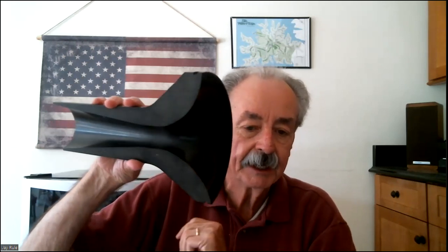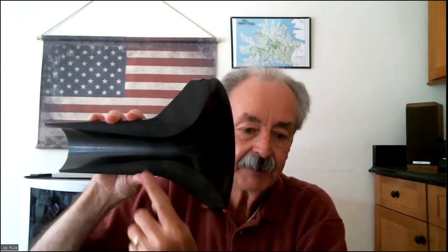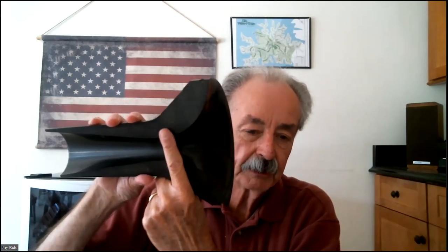Another example of a rocket nozzle, made out of a carbon composite. This is inlet going in, outlet coming out. And then this is a cross-sectional view. So someone's cut this thing right down the middle. And so you can see what this looks like, a converging section to a throat, to the lowest area.